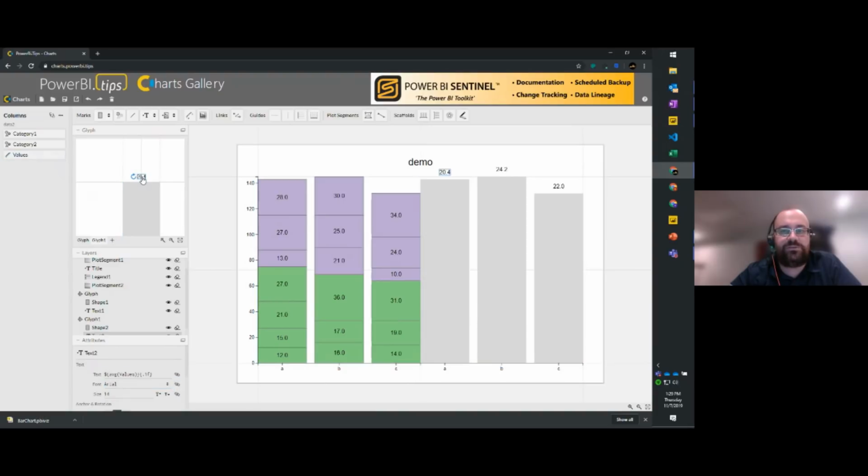I'm going to grab my values and add it here. Now, again, it by default is doing an average of each of these 3 items. So we have to go down here while keeping the text item highlighted, go down to the attributes area, and we're going to modify this code here. I said no code. This is very minor code. Okay, we're going to change it from average to sum. And what that does now is total everything in the same column. So now you have these total columns.